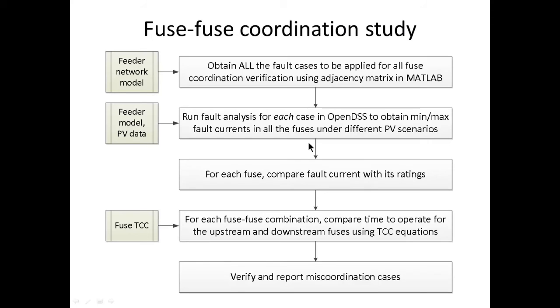Here is a flow chart of the automated method to study the fuse-to-fuse coordination in a given feeder. Starting from this detailed feeder network model, especially the adjacency matrix, using MATLAB we obtain all the possible fault cases relevant for this fuse coordination verification.